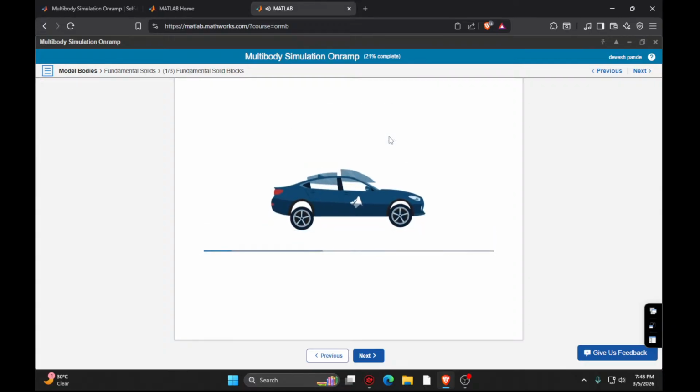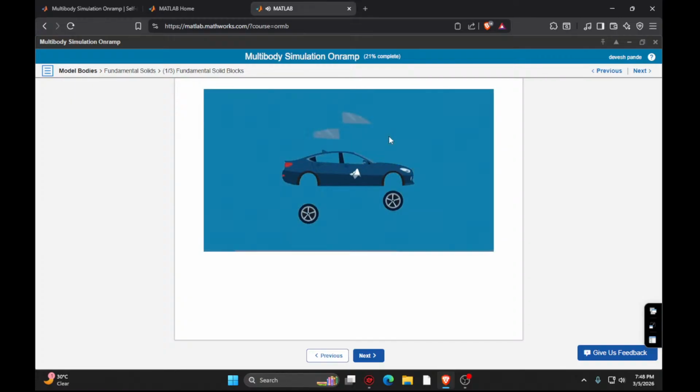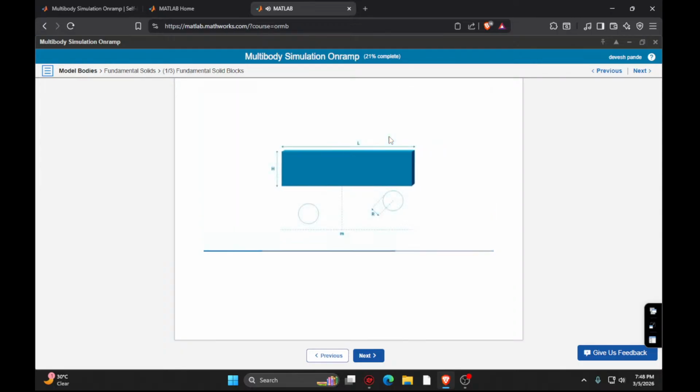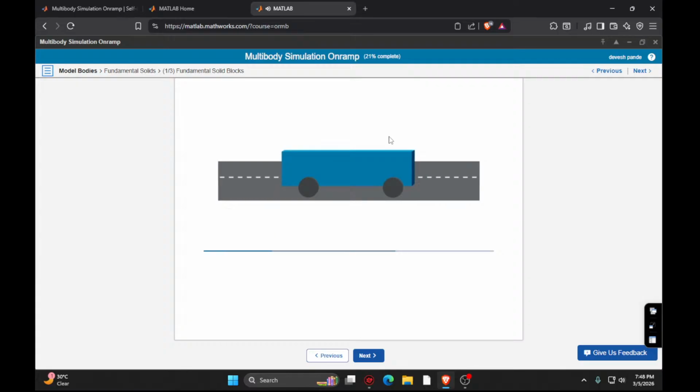Start by breaking down the big task into manageable chunks. Sketch out the car's overall structure, weight, and dimensions, focusing only on the main parts, like the car body and tires. Leave the finer details for later, since they don't significantly affect the vehicle dynamics. For instance, you can use a brick to represent the car's chassis, simple cylinders for the wheels, and bam, you've got a rudimentary car. It may not win any beauty contests, but hey, it can get you where you need to go.